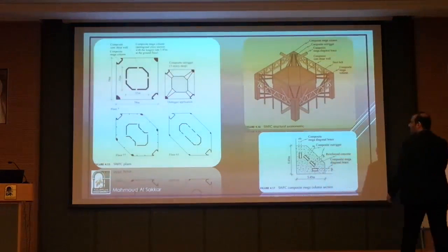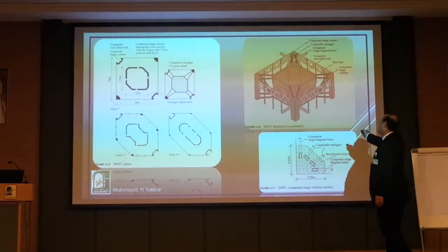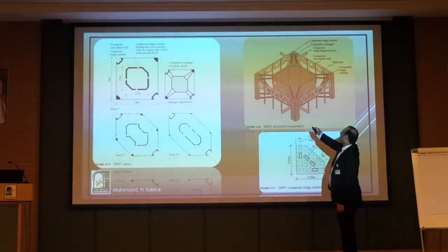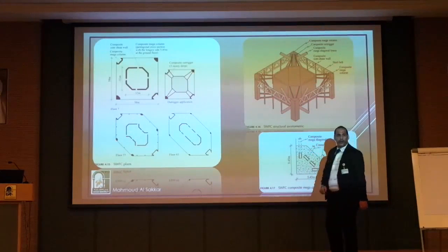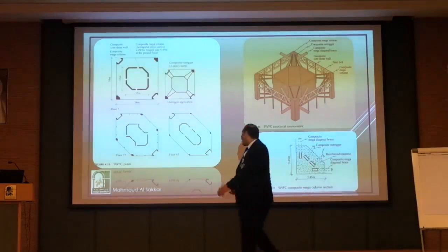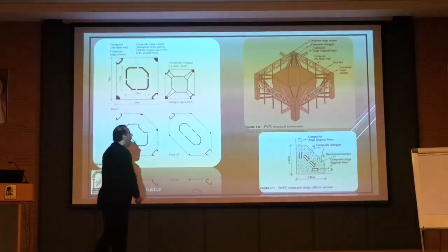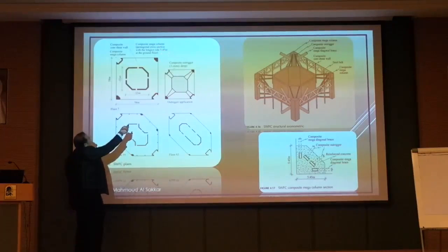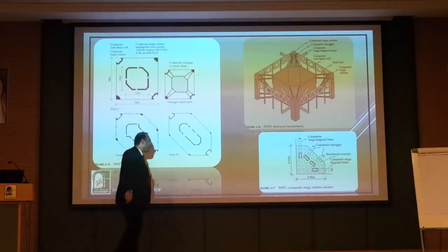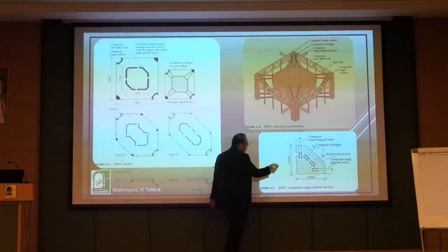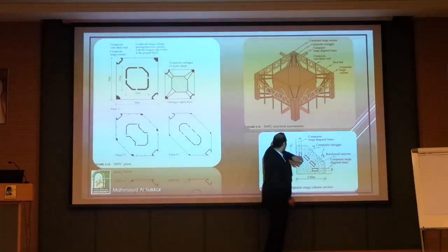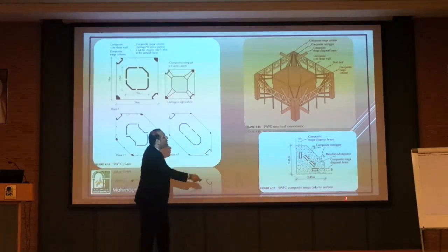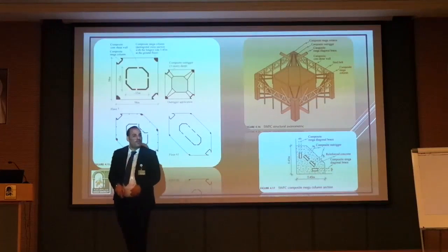We have here, I will start over there, the WFC. The outrigger here is something elegant. Look, they just make brackets over there. It's not a full outrigger; the outrigger is the bracket over there. And we have an outrigger belt, which is a truss. And by the way, we have here a mega column. The mega column is, look, a 5.45 meter column, and it actually included a lot of I-beams inside, or steel sections. It was a mega column and a steel composite column together.